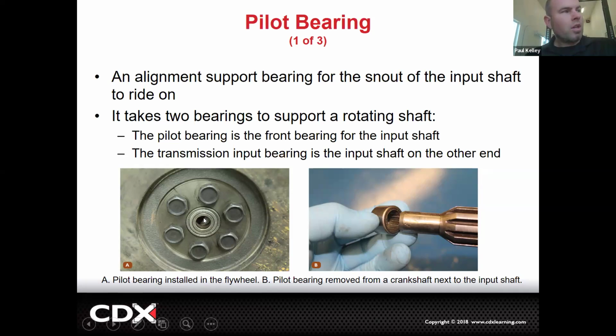It sounds crazy. You pack a bunch of grease in there, and then if you had something like this input shaft, you put it in the center and try to drive it in. It won't go in because the grease functions like a liquid and it'll be basically hydraulically locked, right? So the more you push in, you'll increase the pressure on the grease and the grease will try to push out.